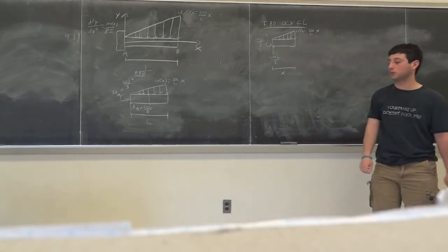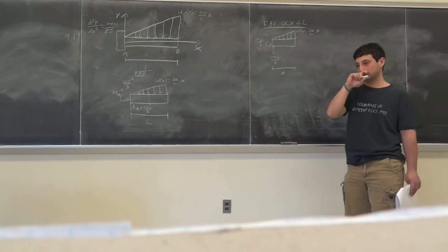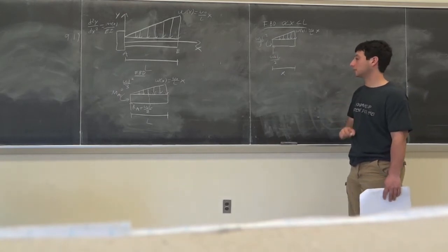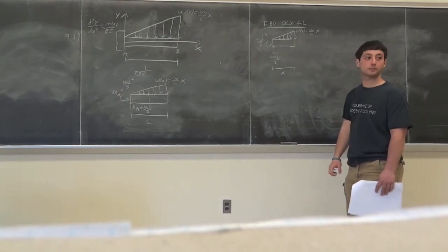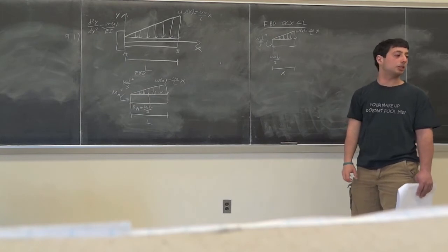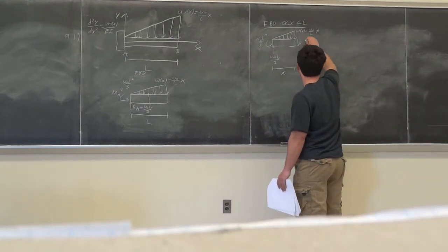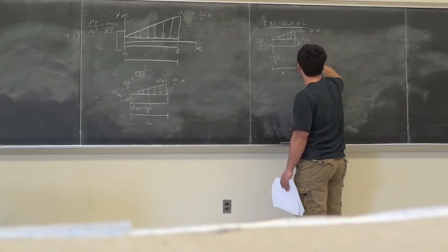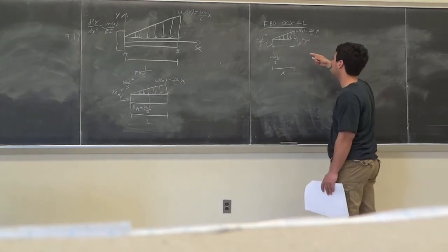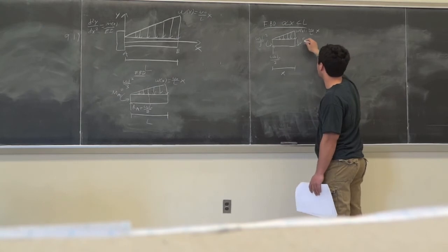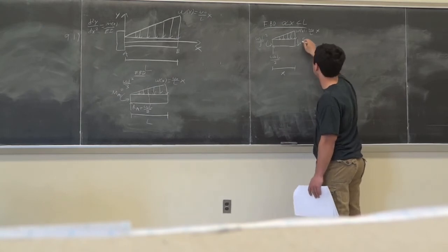So what forces are we going to have at the cut? What type of reactions? Here I have a shear and another moment. A shear and a moment, yeah. Alright, so we have V and M, right? And these depend on x, right? Okay, so in this section, I'm going to call this V sub x.